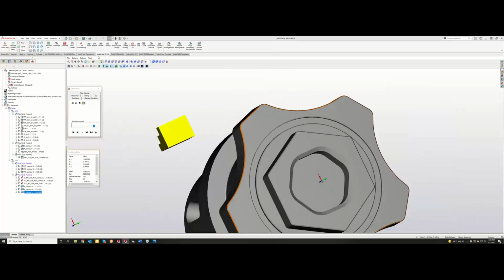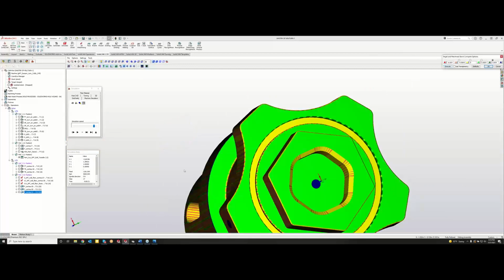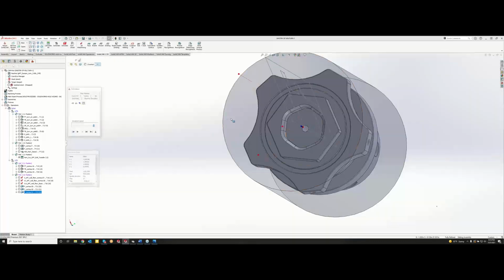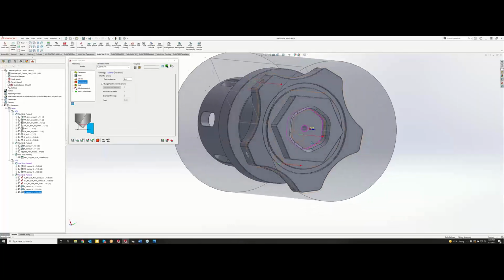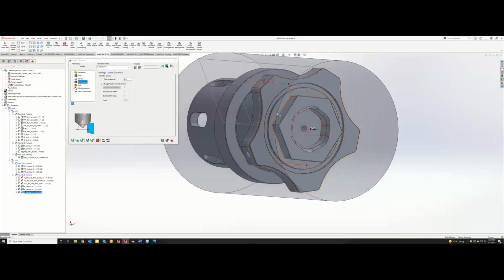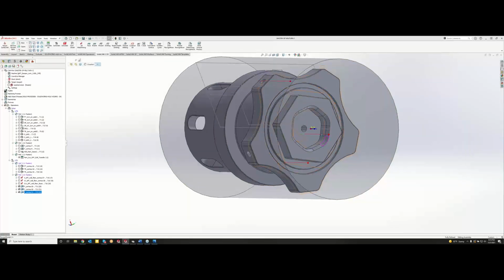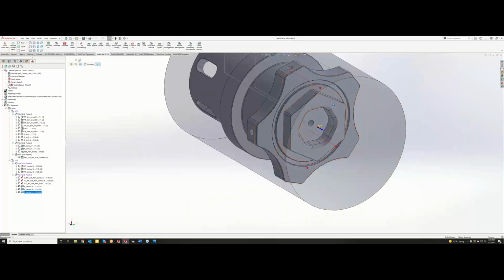Got our chamfer going all the way around. Double check it real quick. We're golden. Okay. Now, the only other thing that we have left on this part here is doing our drilled holes. Okay. So now, what we can do in here is we need to, and we're going to be doing this on the sub spindle.